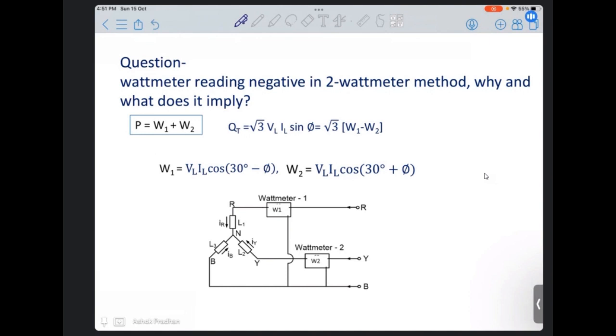Today all digital meters measure the three-phase voltages and currents too. So it is like a theoretical thing. But still, in books many might be teaching it, and it can give some concept. You can say that a single phase wattmeter, digital wattmeter, you can put, and you can put questions also. Whatever it may be, we see that the Q here equals root 3 (W1 minus W2) for this arrangement.